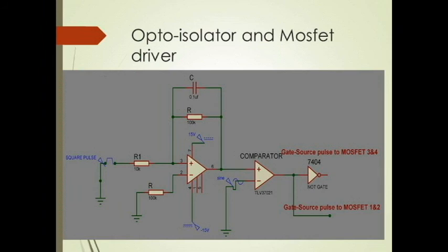Since the controller is connected to various points in the system, the ground of PWM pulse given to MOSFET needs to be isolated from the ground of the controller which might be connected elsewhere in the system. An opto-isolator is used to achieve this. A MOSFET driver is inserted between the isolator and MOSFET, which helps in providing power to drive the MOSFET and also reduce the switch on time and switch off time of the MOSFET.